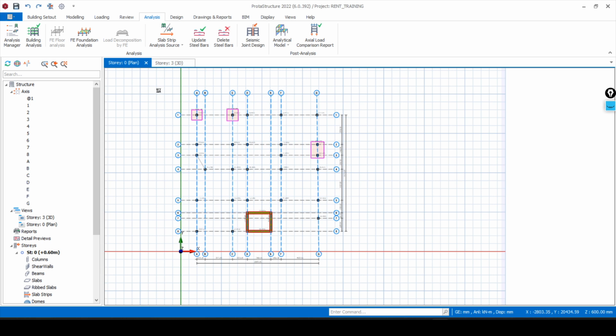Engineer Chinatulun Jidofo asks: what if the footing size is too large? Now that is where our advanced session comes in. So when you are getting the footing size to be too large, giving you values like 10 meters by 10 meters and all that, it is not reasonable at all. What that simply means is that your pad foundation may not be suitable for that structure.